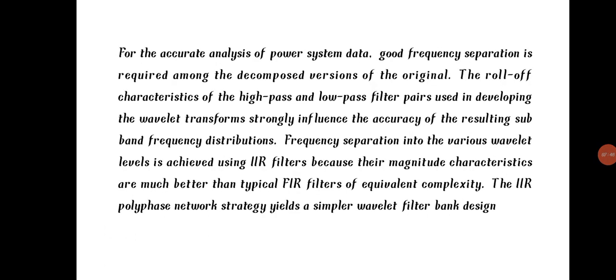For accurate analysis of power system data, good frequency separation is required among the decomposed subbands. The roll-off characteristics of the high pass and low pass filter pairs used in developing the wavelet transform strongly influence the accuracy of the resulting subband frequency distributions.